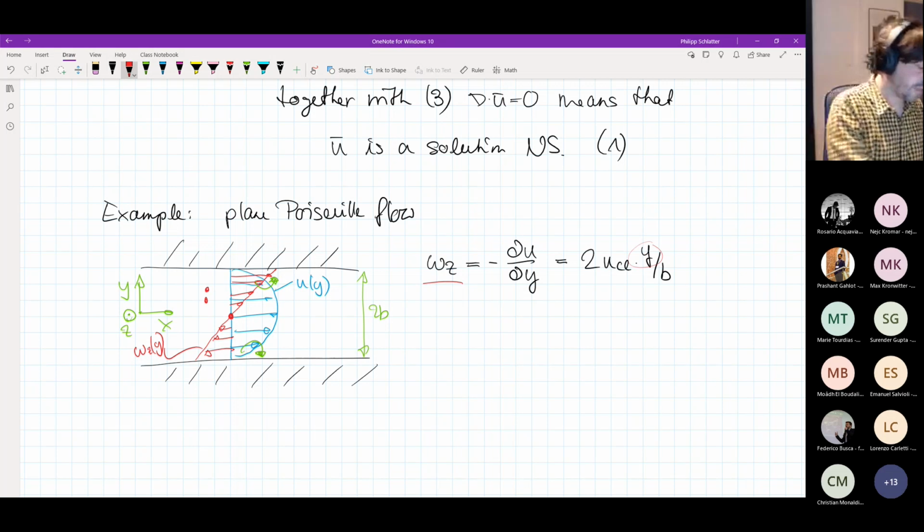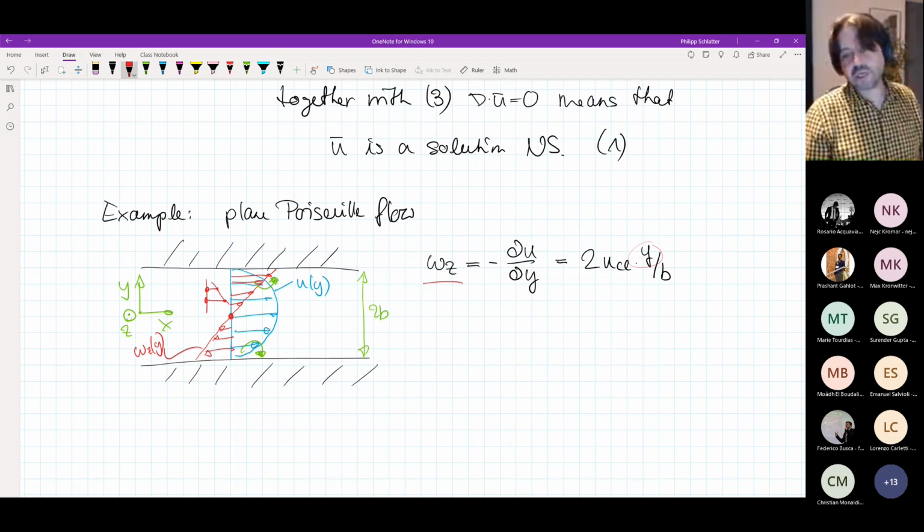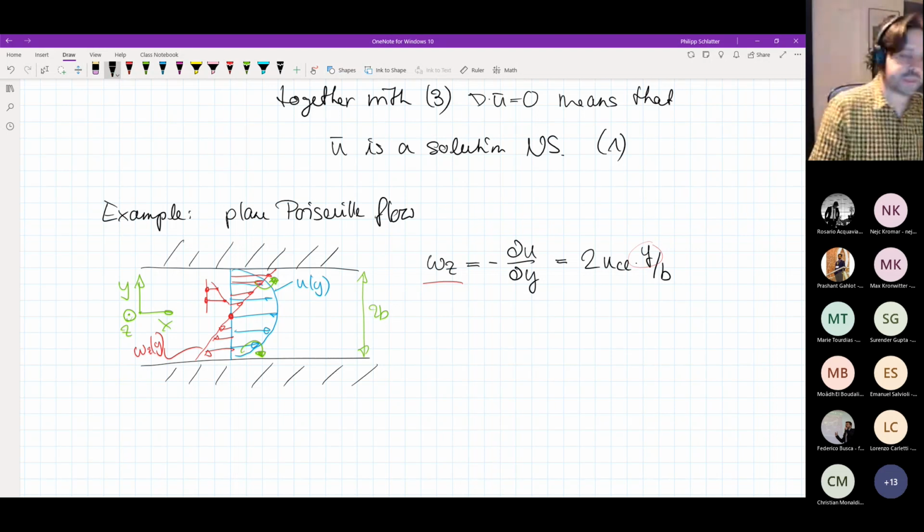So later on, maybe this has traveled here and this has traveled here. So this vertical line suddenly became a little bit tilted. And of course, it has become tilted exactly in the way we predicted with how this rotation would look like. So you can essentially identify the vorticity as a change of orientation of a fluid particle in the flow, as a kind of local rotation that the fluid particle would experience.